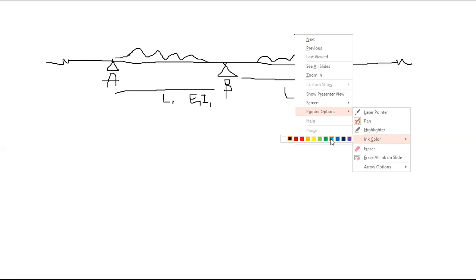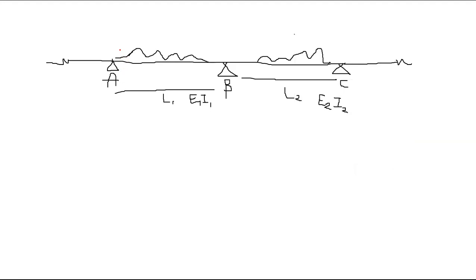So what you need to solve in this beam is, if you can find these support bending moments, right? So you can probably separate each span from that support and solve just like you did in moment distribution, right? Okay, so this is given by one equation in this case. So let's say this is M1, okay? So let's say the bending moment is, so if it is continuous,